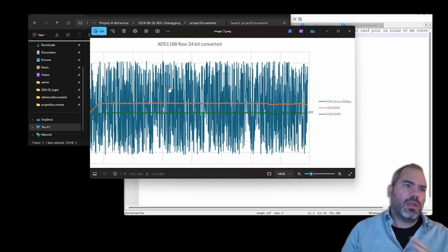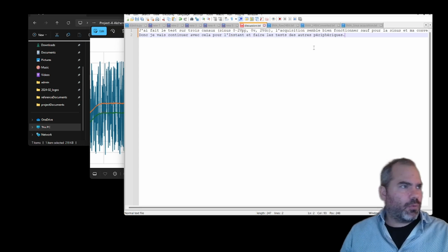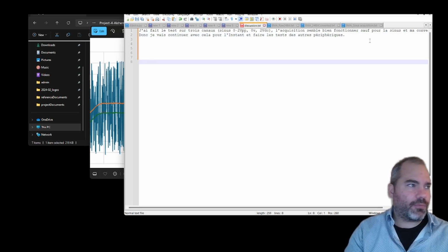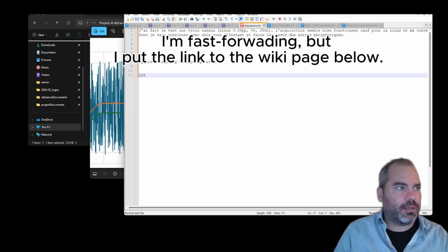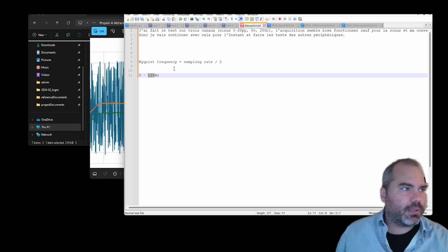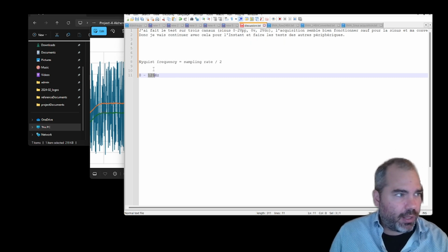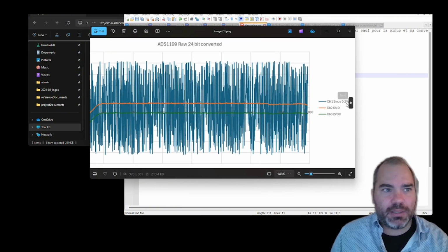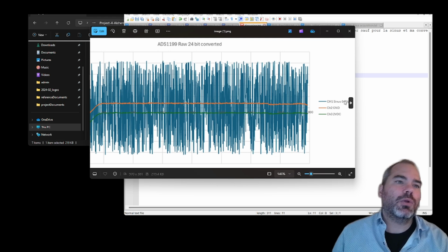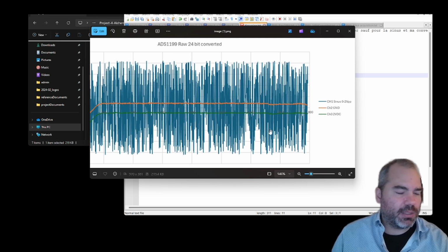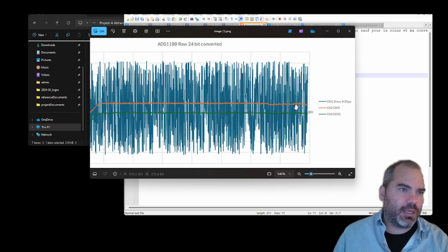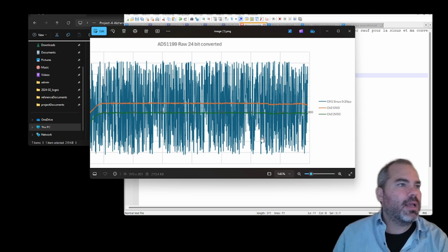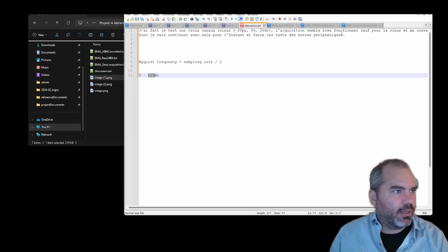That's the Nyquist frequency. So 50 hertz is well within our bandwidth, and we shouldn't meet issues sampling 0.2 volts peak to peak. Now we see all these oscillations. It does show that it's not a straight line, and this is the starting point of what we have.